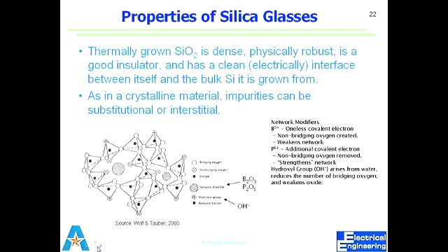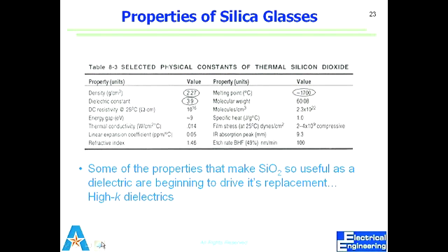So, what happens in wet oxide is we have many more hydroxyl groups which weaken the structure, right? So that's the fundamental reason why wet oxide is fast, but electrically not good. Electrically it can result in tunneling and needs a thicker film than a dry oxide, where we can thin it and still not see any tunneling of current. Okay. Right? So these are important considerations once we are looking at the